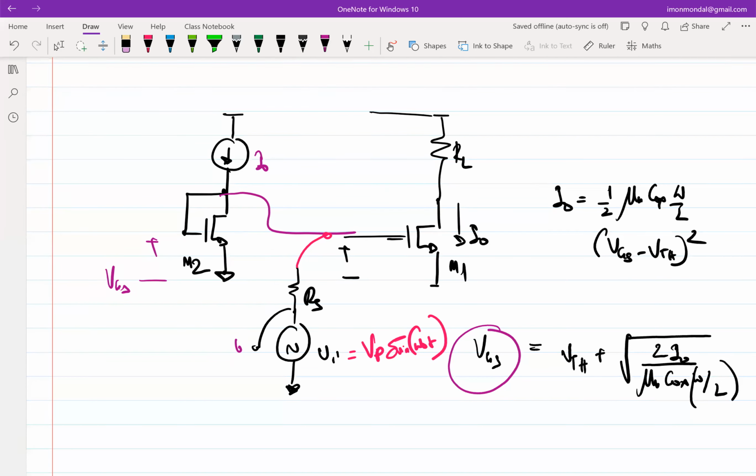The stuff that you have added is loading your bias point. So when it loads, what will it do? Capacitor, right? You have an infinite capacitor. You put an infinite capacitor here, let's call it CB. So we put a blocking capacitor here, which blocks the quiescent current from flowing out.